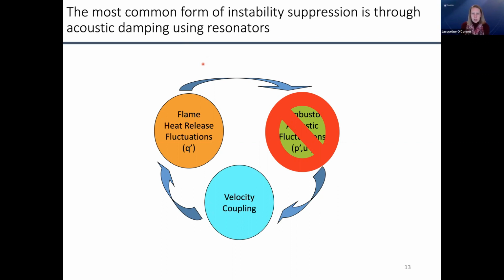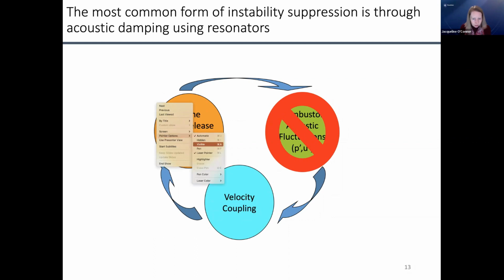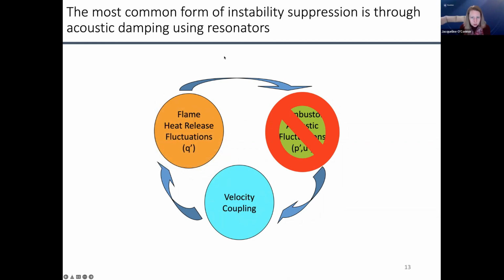And like I mentioned previously, if you have an instability that is changing, well, mostly frequency, as you change season, fuel composition, humidity, weather, gnomes in your fuel system, whatever it is, then your acoustic damping also has to be able to change with those.